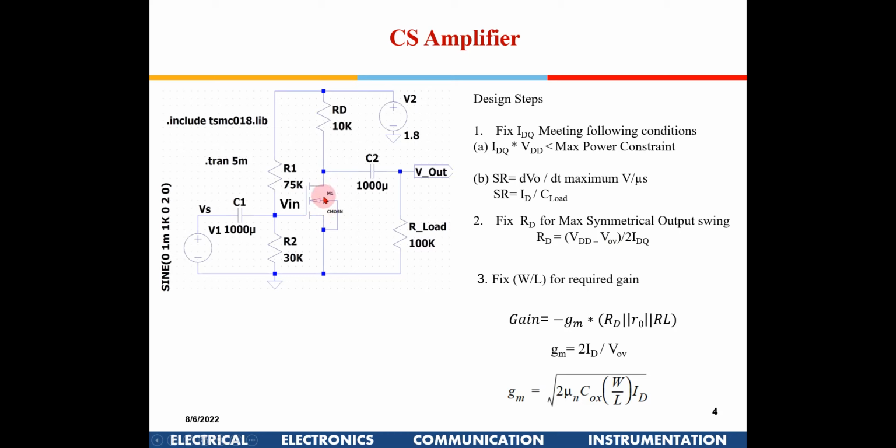We can do that, but generally we should avoid operating close to VDD and 0 swings, because non-linearity sets in. If you require an output voltage from 0 to 1 volt, it is better to go for a higher supply voltage circuit rather than trying to reach close to 1.8 volt. You see here GM is ID, and we are assuming the bias current is ID and there is a small change in current.